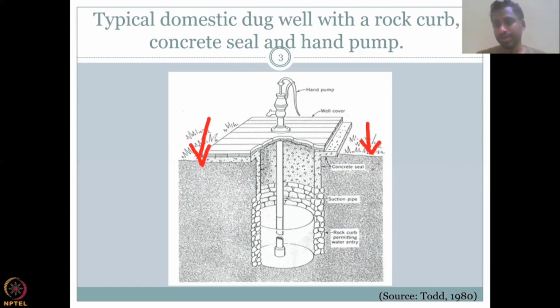And also, for example, if it is near the Ganges, you see a lot of hand pumps. And if the Ganges is polluted, then what can happen is water can come through like this. So to prevent that, they have kept a concrete seal, a wall, and water doesn't flow through. There is seepage, very, very little. And once it is old, the concrete can break. But for newly constructed wells, well-maintained wells, you don't have water movement through the concrete. And it can go as deep as needed depending on the taste and quality of the water.